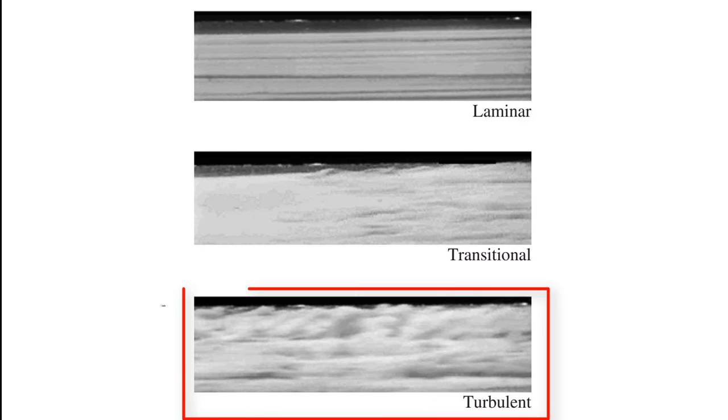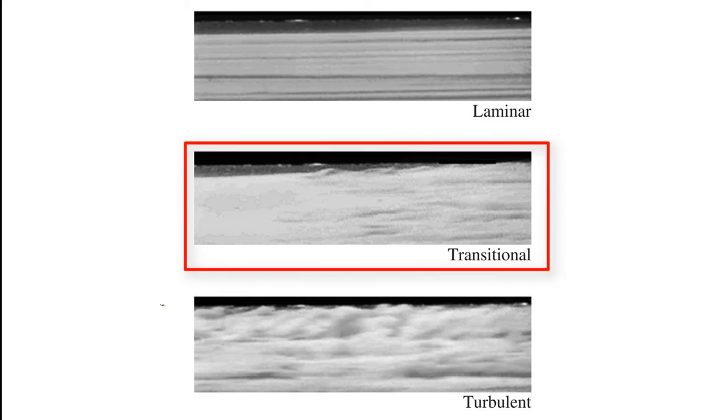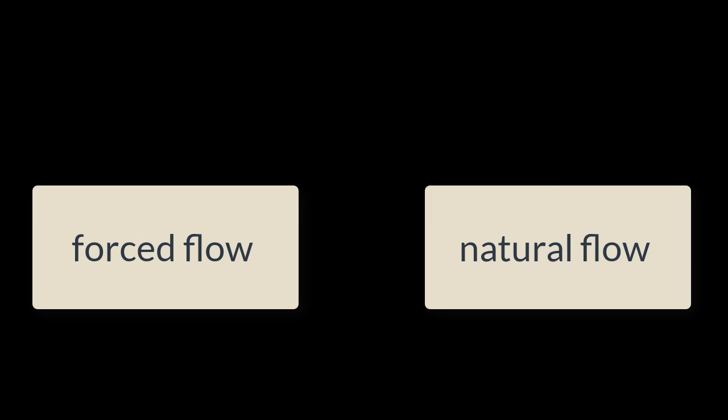The highly disordered fluid motion that typically occurs at high velocities and is characterized by velocity fluctuations is called turbulent. The flow of low viscosity fluids such as air at high velocities is typically turbulent. The flow regime greatly influences the required power for pumping. A flow that alternates between being laminar and turbulent is called transitional. The experiments conducted by Osborne Reynolds in the 1880s resulted in the establishment of the dimensionless Reynolds number, Re, as the key parameter for the determination of the flow regime in pipes.